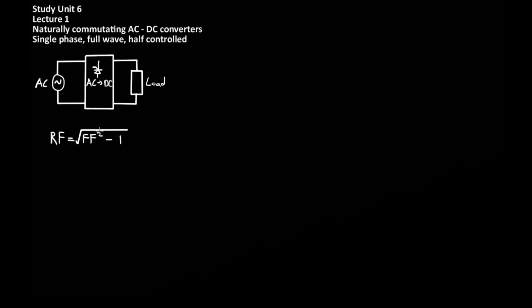So shown here is figure 12.1 from the reference text, and it shows 4 different AC to DC converter circuits. These circuits all produce a continuous voltage with variable output current, and what sets them apart is how the conversion bridge has been built. They all use a combination of thyristors and diodes. For example, circuit A here has 4 thyristor devices, circuit C here has 2 thyristors and 2 diodes, as does D, and circuit B has 2 thyristors and a single diode, but makes use of a transformer that is center tapped to reduce the number of active devices.